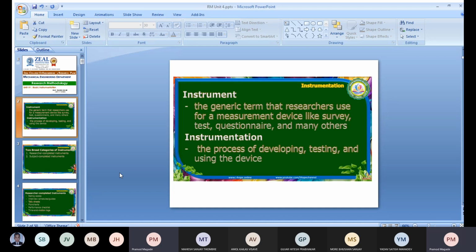Correct? Suppose I'm developing a spring. I want to design a spring. So I will have to calculate its stiffness. And for stiffness, I have to calculate K. K is equal to W by delta, the load applied with respect to deflection. So that answer is theoretical. But on the actual spring, I will have to calculate whatever the stiffness is. So a stiffness meter is also there, through which we'll have to check.